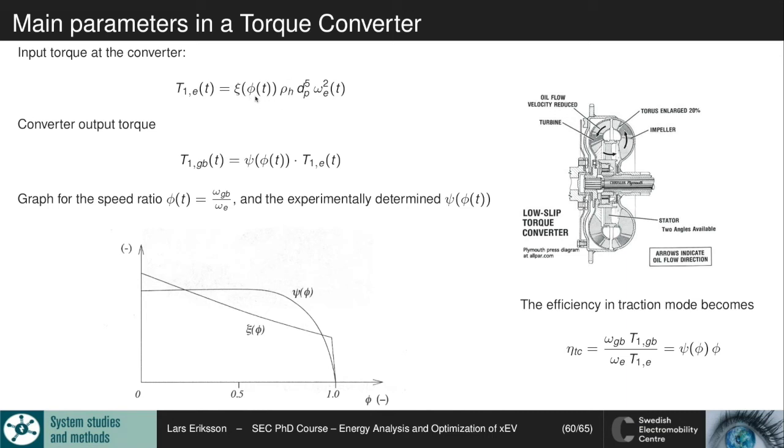And the modeling of an automatic transmission is done with the aid of 3 things. We have a slip here, and the slip is seen here. So 1 means that we have the same speed on the input and output side. So that's this part here. And then we have a torque loading curve that relates to the input speed. And we have the input speed here, and we have that torque loading curve that is illustrated here. That one tells how much torque we will be consuming on the input side. And when we come to the output side, so we have the slip, we have this psi here, and then we have the psi here that also depend on the slip factor.